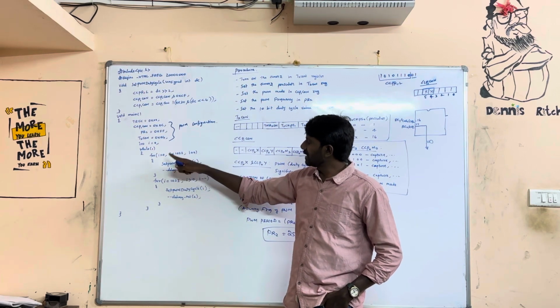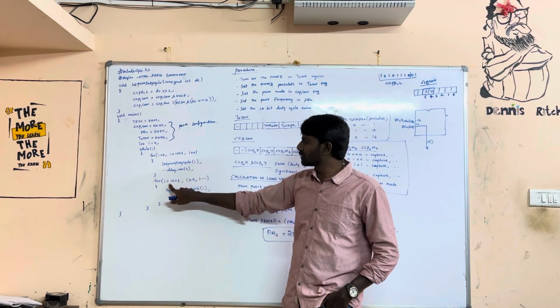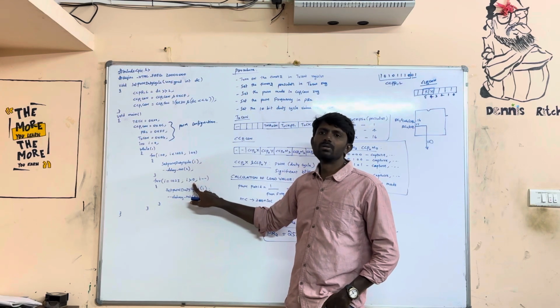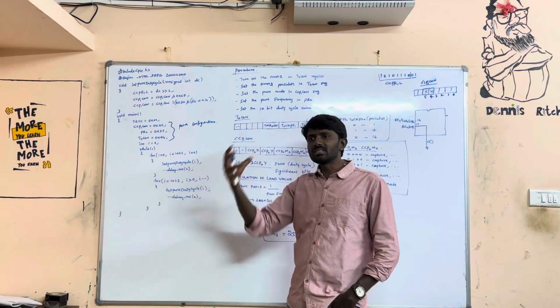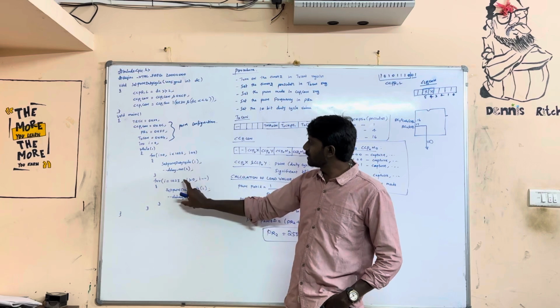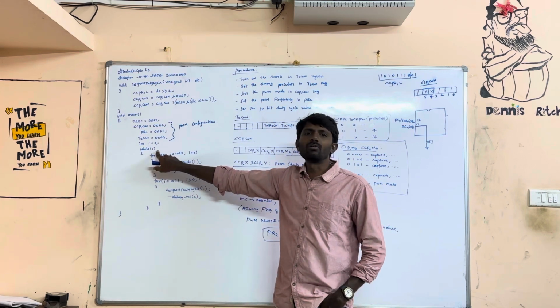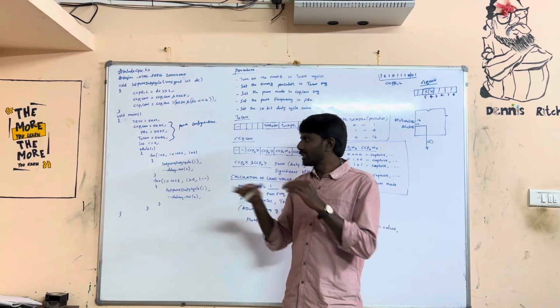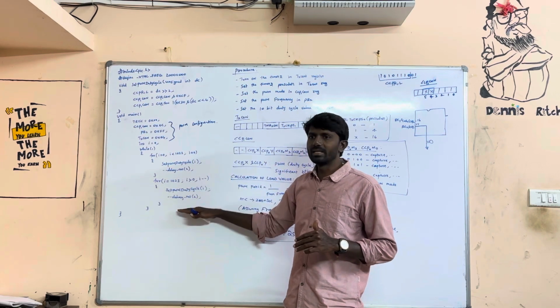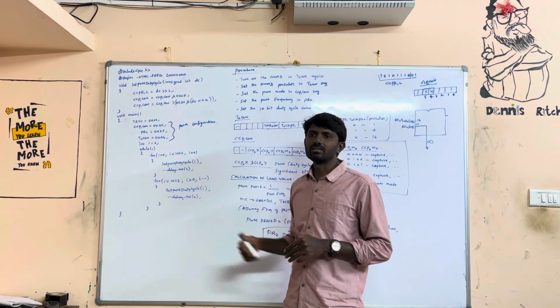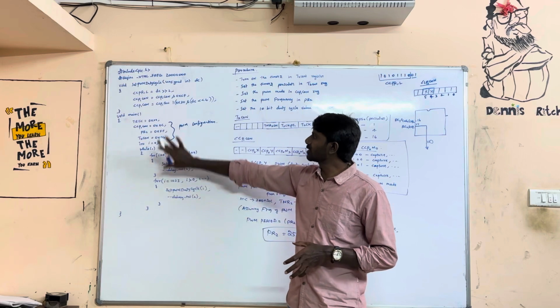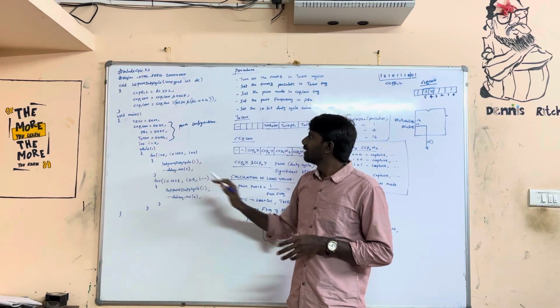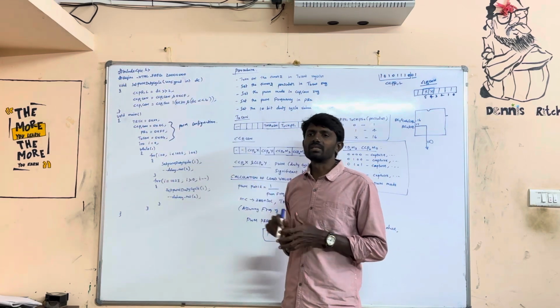Next, once the loop is completed, it comes here again. Now from 1023, it goes down to 0. So now the brightness is reducing. Both loops are inside the infinite while loop. So gradually it is increasing, then gradually decreasing, again increasing, decreasing. Clear? So the overall experiment is only that much. And the function for setting the duty cycle we have already seen.